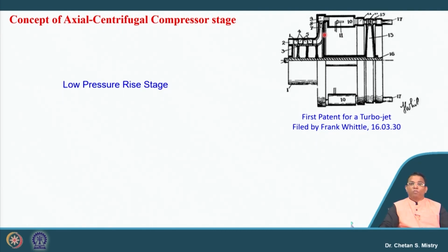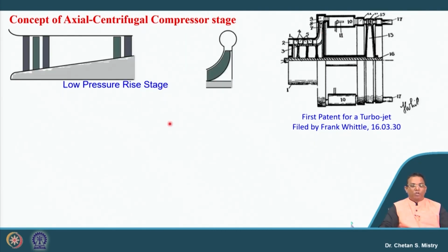Suppose I say I am looking for a low pressure ratio, this represents my low pressure ratio stage. So I will be having a number of axial flow compressor stages. As we have discussed, since I am having the problem with the fragile body, because of the aerofoil, which has more chances for flow separation, in order to avoid that situation we are having the number of stages to be higher.